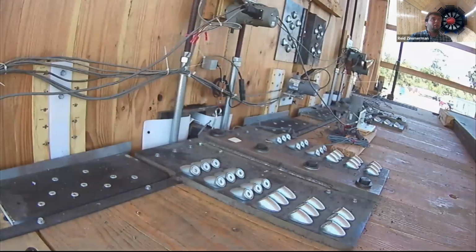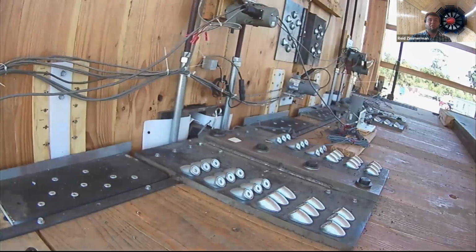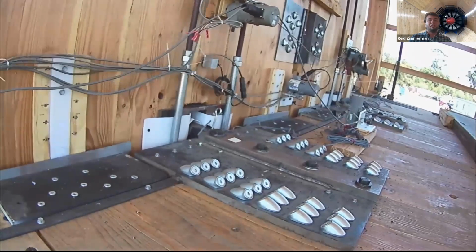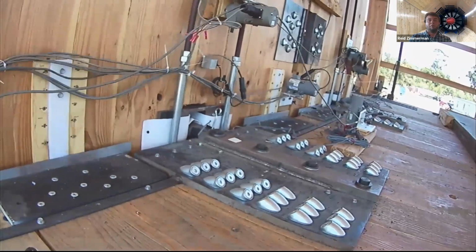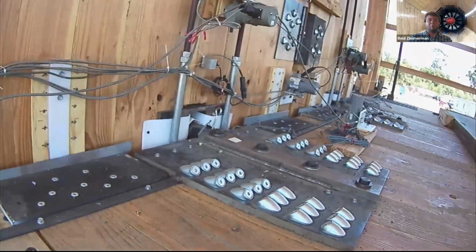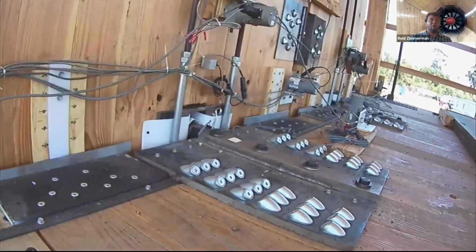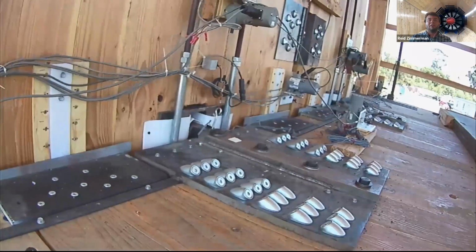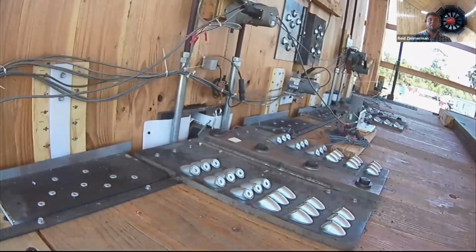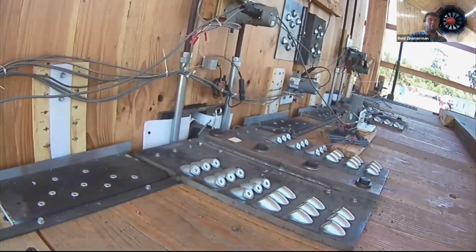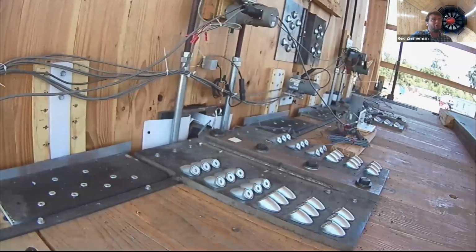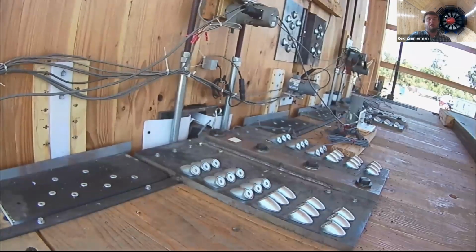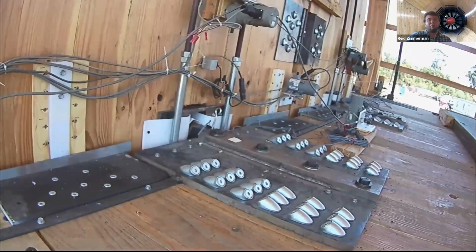So this video I'm showing is from actually the NHERI 2-story test, which you're going to hear about in a couple of weeks at the next meetup, showing the performance of this tongue connection, this diaphragm to wall connection. As the wall, you can see here, I'm hearing lots of sound, but you're not. As the wall is rocking up past the floor, no connection really between the floor and the wall other than this strong tongue connection, which basically transfers horizontal shear, but no other forces or minimal other forces.